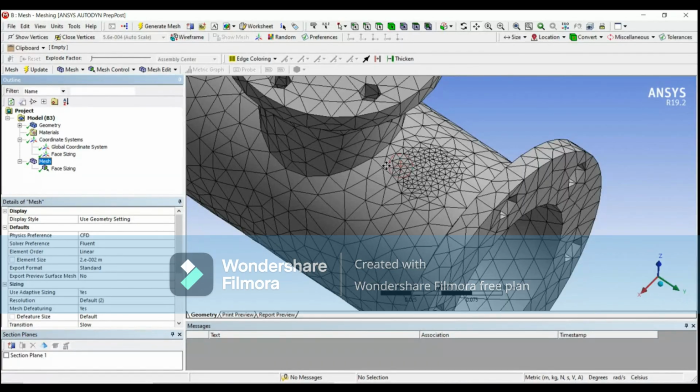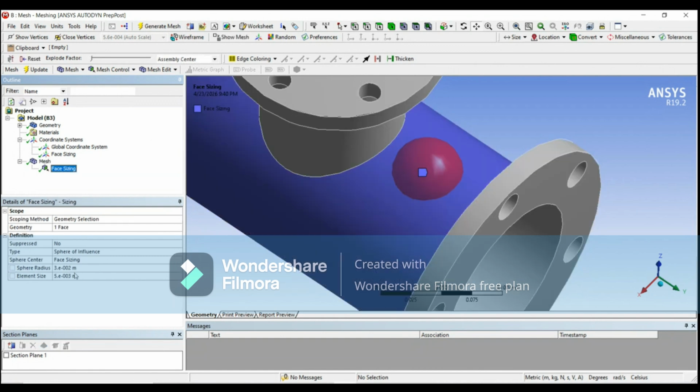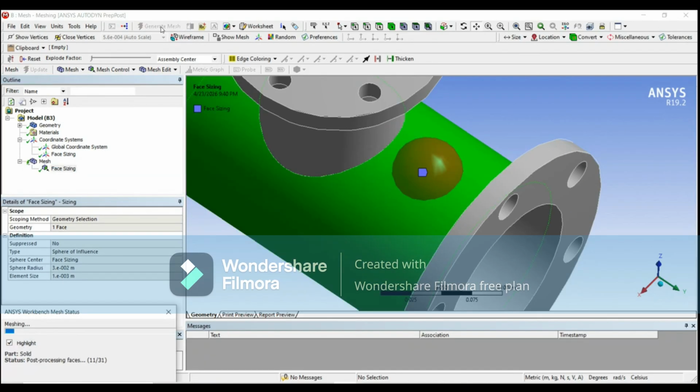Whenever we want to apply a sphere of influence, we have to turn off the advanced size function like curvature and proximity. Again, we can make it much more fine so that it looks much better, and we can generate the mesh.